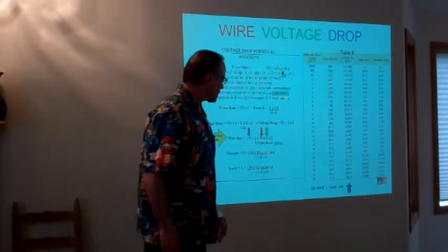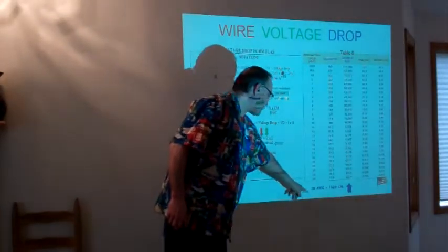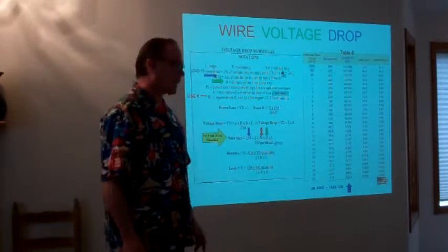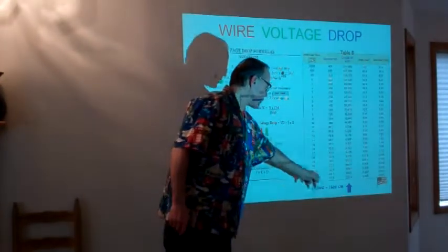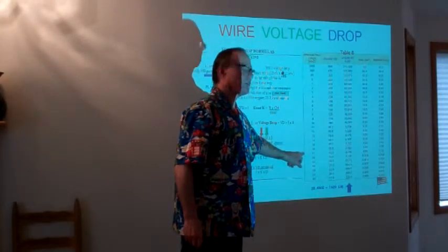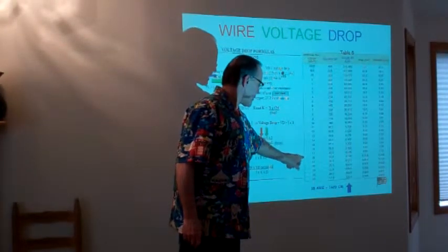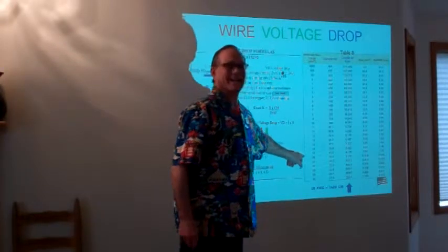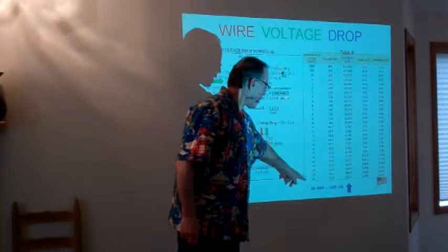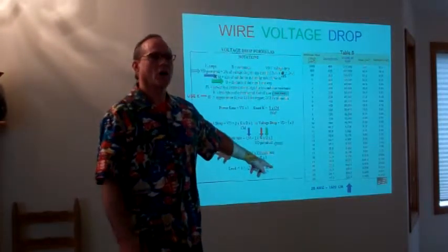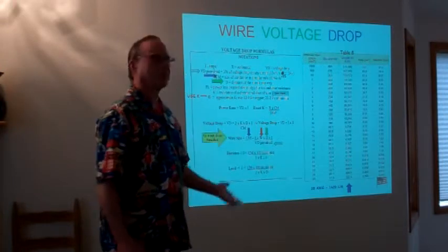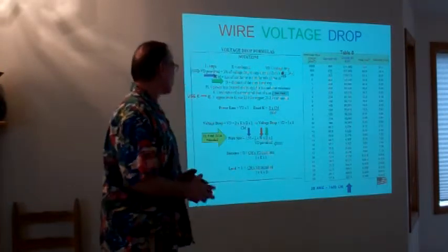You'll notice that I have to point this out to you. I've got another one down here, 18 AWG, which stands for American Wire Gauge, and the circular mils for that is 1620. Well, if you notice in the chart I had, there's a little snafu. 18 and actually 19 are missing, but 19 gauge wire is hardly ever used. The 18 gauge is very much more common for us to use. So I included this in this chart so you'd be able to utilize our formula as we're going to see.